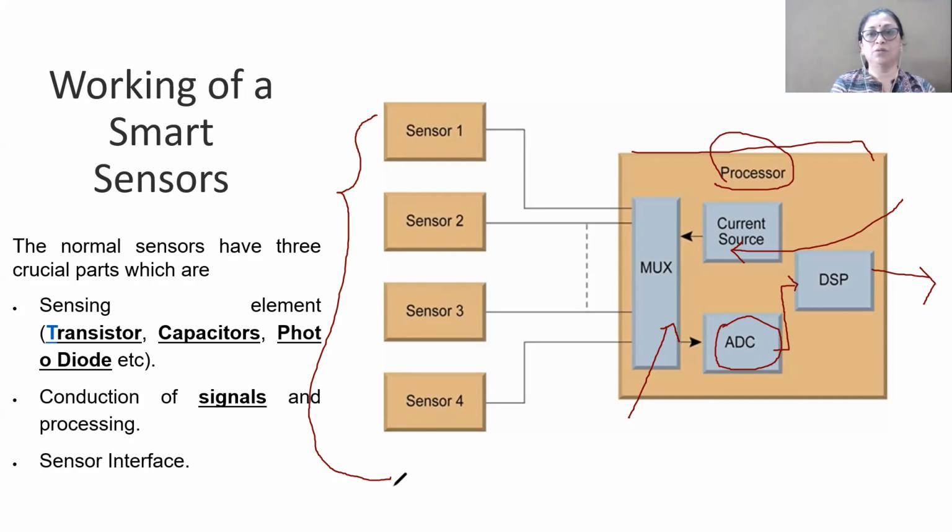The output of each sensor is to be provided based on the time division multiplexing concept. A certain time slot is provided for each sensor, and during that time slot, a particular sensor will provide its output to the user. Continuously, the slot will be provided to all these sensors, and this frame is repeated continuously.